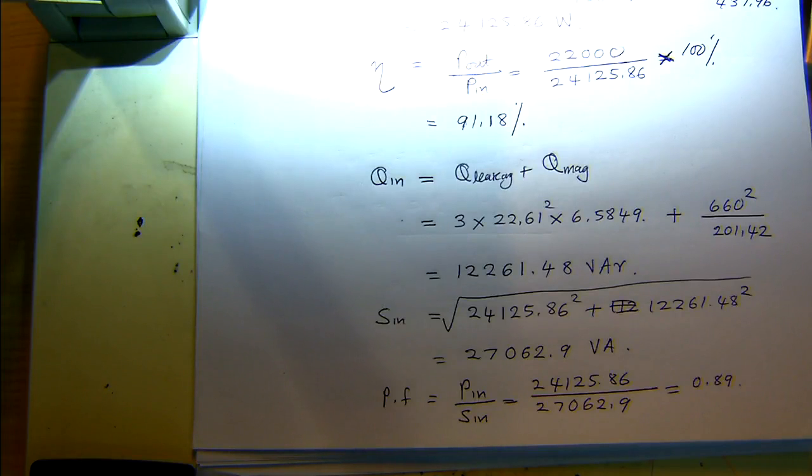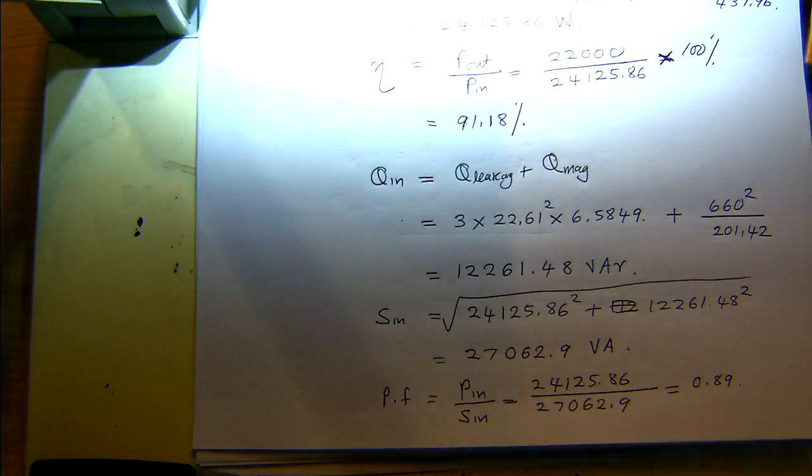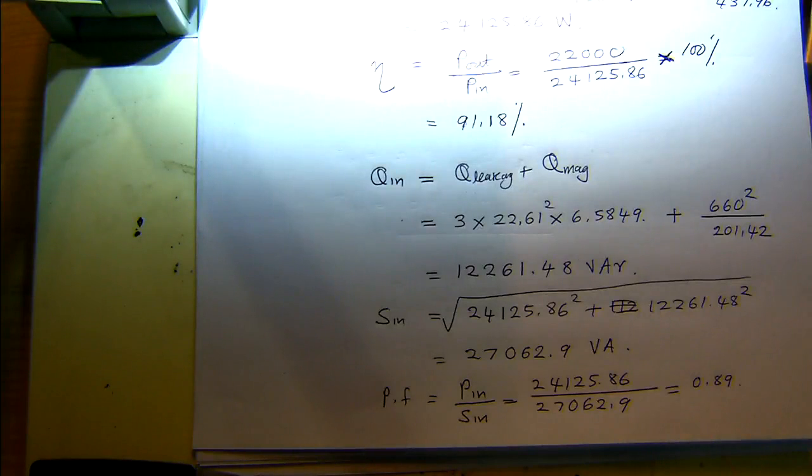So since we are running out of time, I'll probably skip the second one. So I'll upload the answers to the Canvas. The second part, pretty much you need to reduce the voltage and put in the slip value. So it'll be pretty much the similar calculation to the tutorial 1, 2, 3 questions. So different voltage, given the slip, you need to calculate the current and the phase angle of the current.